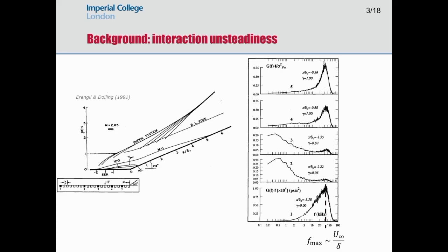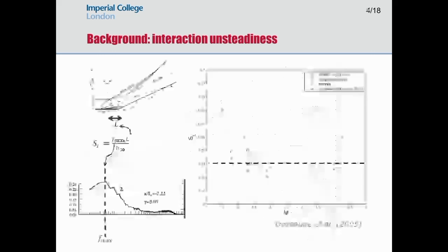So if your shock is oscillating at a low frequency, this is associated with a large amplitude motion. And again, across the shock, you have that big jump in pressure. So that's going to fatigue your engine intake, for example.